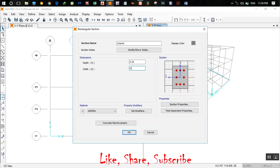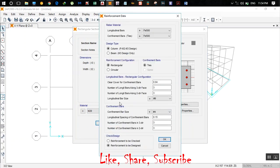The width is 0.35, the material I'll be taking is M20, and for concrete reinforcement, longitudinal bars are FE500 and confinement bars are also FE500. The design type is column. The reinforcement configuration is rectangular, and the clear cover for confinement bars is 40 mm, which is fine.